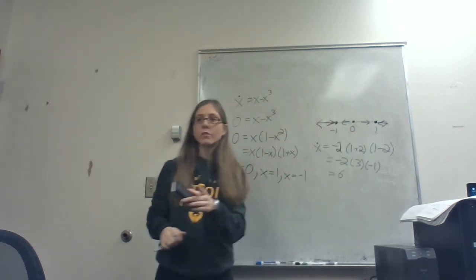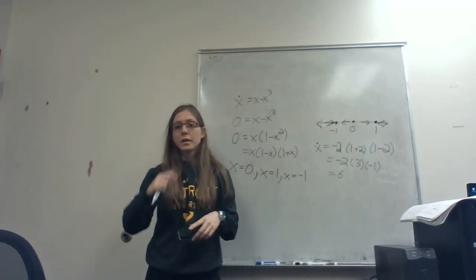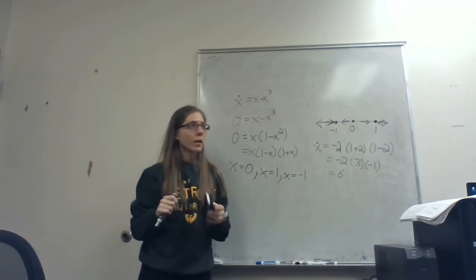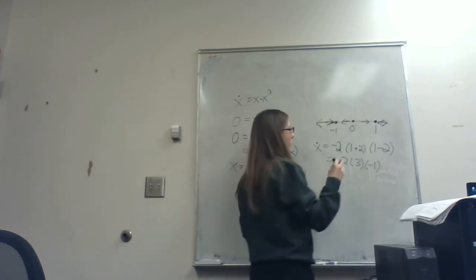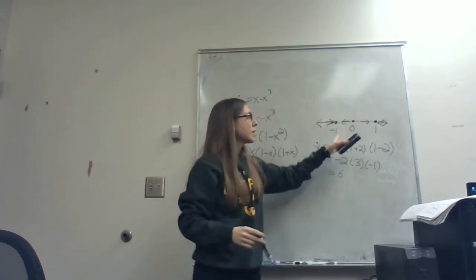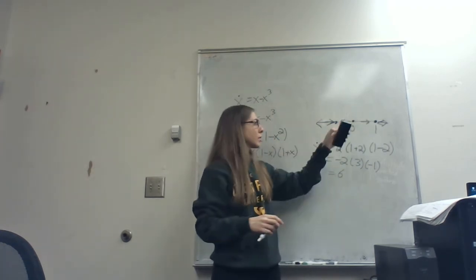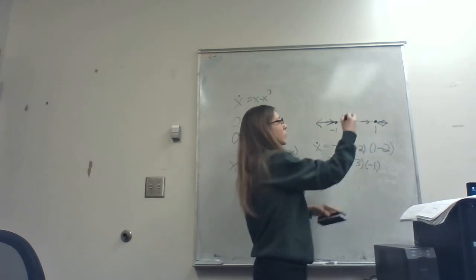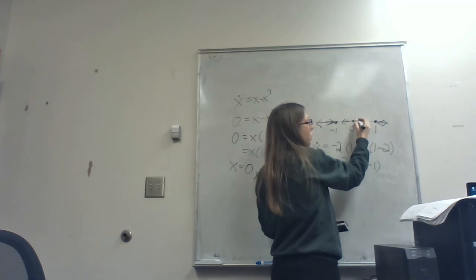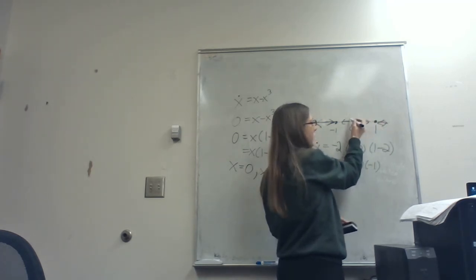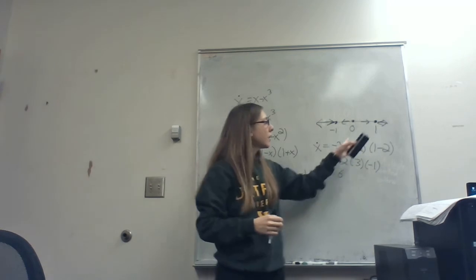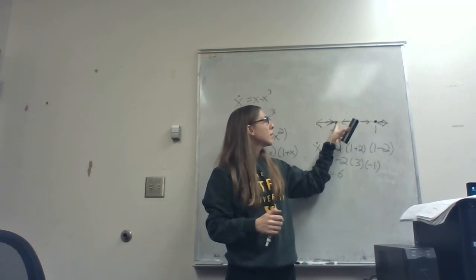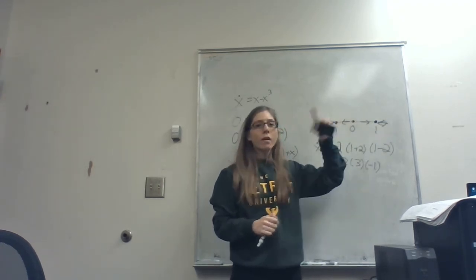So you know how you cover stability in undergrad control, and then you say, does the state go to the origin, or what happens when it's perturbed. So if you want to look at stability, some of the questions are, you only focus on equilibria in nonlinear systems. Because say this was true for a minute, just pretend. I don't know, I haven't checked. But if, for example, every solution starting at 0 stays at 0, and every solution infinitesimally off of 0 goes to 1 if it's on this side of 0, goes to -1 if it's on that side of 0, then 0 is an unstable equilibrium. But this system is not unstable because the solutions are going to -1 and 1. So there are stable equilibria.